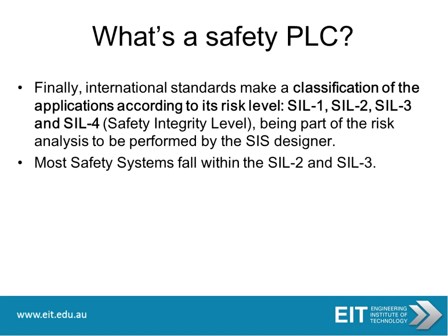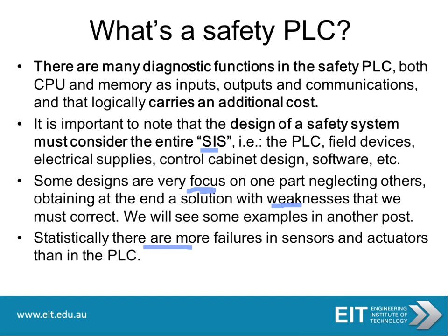Finally, international standards make a classification of the applications according to their risk level. We already looked at SIL 1, 2, 3, and 4, and that's been part of the risk analysis to be performed by the SIS designer. So most of your safety systems fall within SIL 2 and 3, as we've pointed out when we looked at the percentages.